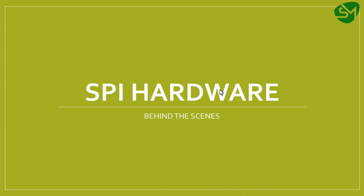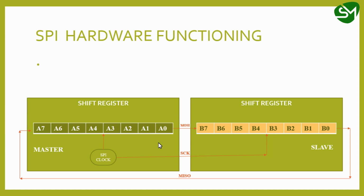So let's understand the data transmission and reception in the SPI hardware. Let's understand this with an animation. You can see this one is the master device and this one is the slave, and this is the MOSI pin and this one is the MISO pin. The master produces the clock to the slave, and byte A, that is A0 to A7, is available in the master, and byte B, that is B0 to B7, is available in the slave.